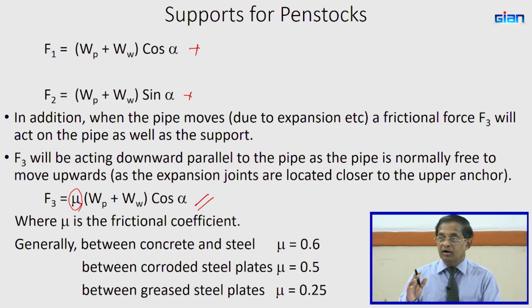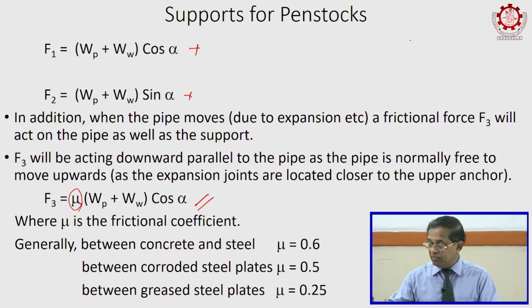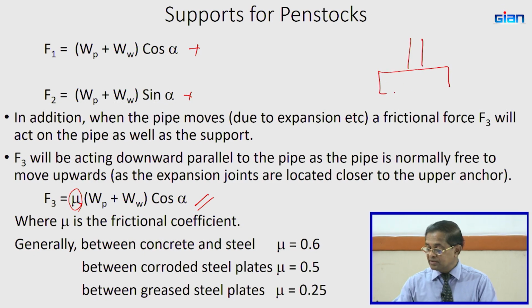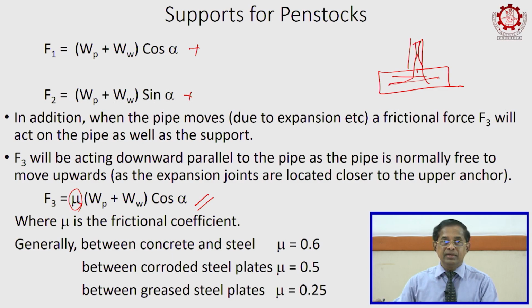So, we have to tell the civil engineer that in the design of the support he should take all these things into consideration, because he might not be aware of the penstock movements, expansion and everything. We have to tell him these are the forces that will come, and accordingly design the support. So, the support will have a good base and sufficient reinforcement to bear all these forces.